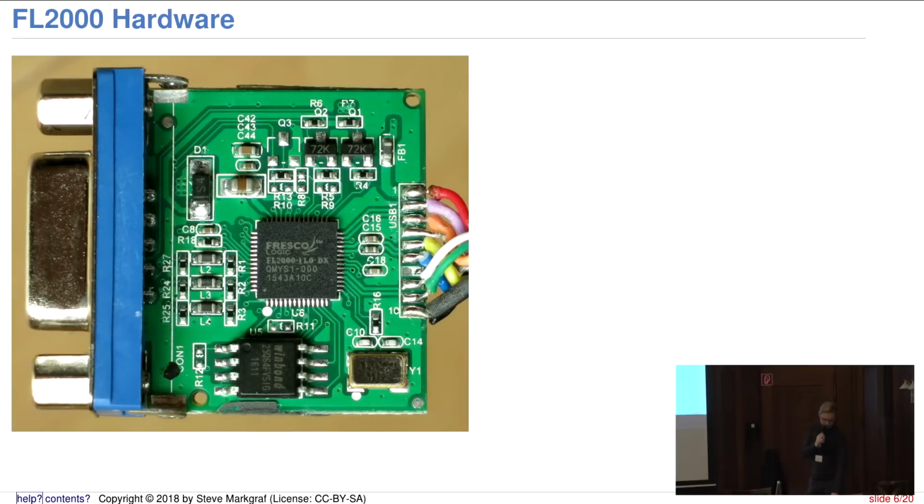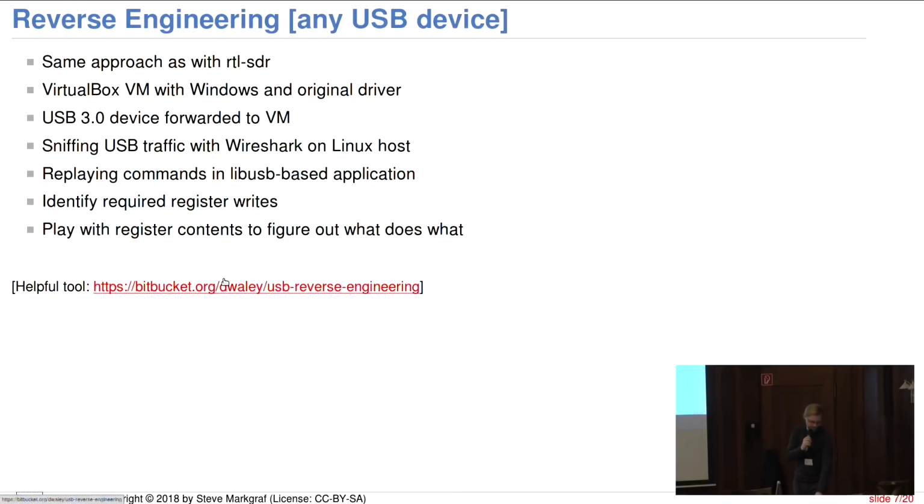In this case, you also can see an SPI EEPROM or flash, which in this case is an 8 megabyte flash which holds the Windows driver. So it also doubles as a mass storage device, so you do not need to download some driver from the website. It's on there, but typically the cheaper versions of those adapters do not have this flash because it costs money, of course. Otherwise it's very simple. There's some filtering going on, and 2 voltage regulators, and that's about it.